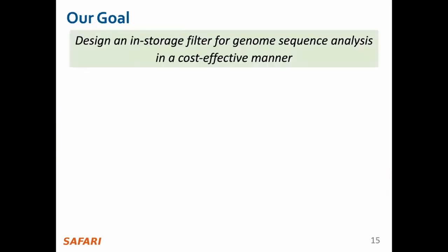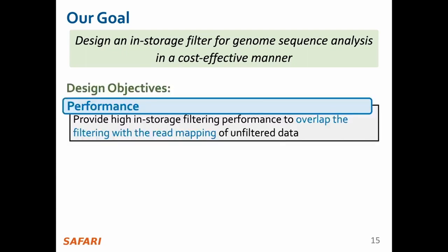So based on these observations and motivated by these studies, our goal is to design a storage filter for genome sequence analysis in a cost-effective manner. And to do that, we have three key design objectives in mind. First is to provide high performance of storage filtering by overlapping the filtering process in the SSD with the read mapping of filtered data. So we want to send the unfiltered data meanwhile to the system that performs read mapping, while we are performing filtering inside the SSD.